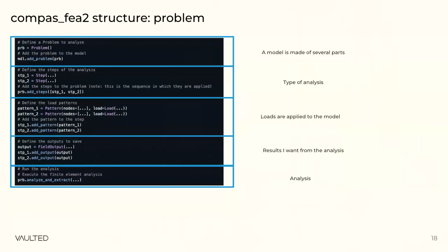Then this is defined. Then I apply my problem. So my problem, it's a specific kind of analysis. Is it a heat analysis, the impact of temperature, or is it a structural static one? Well, so it's more about loading. I define the loads. Then I say, what do I want to know from that model? So is it the results I want? And then I do the analysis to get the results.